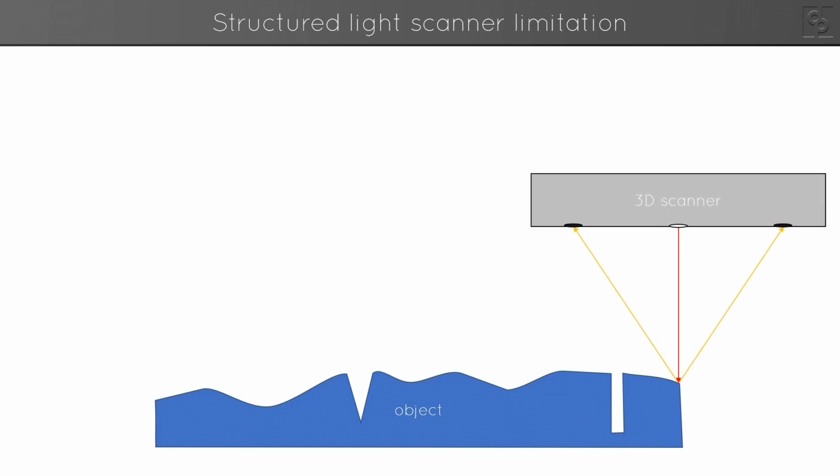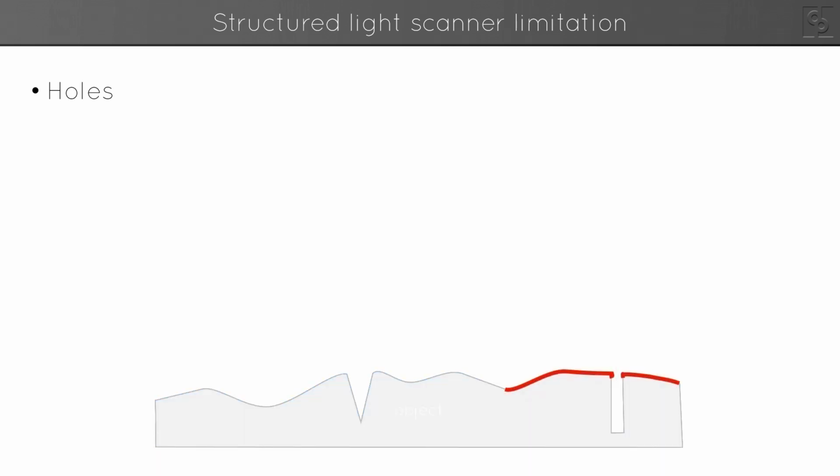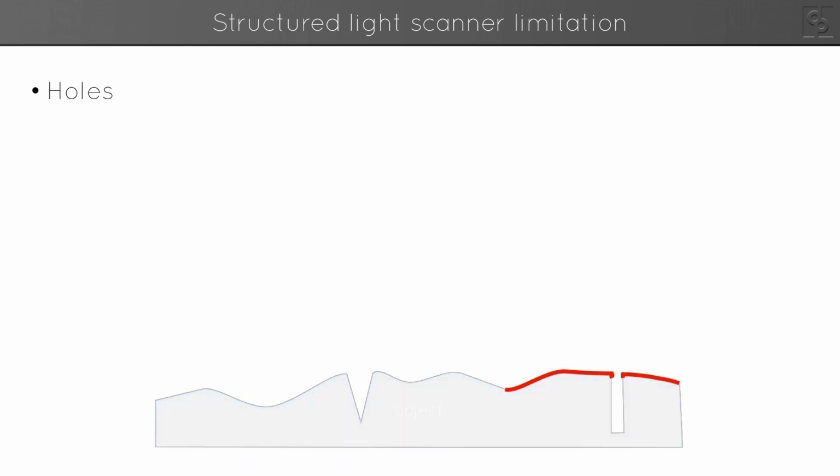When you're scanning a small hole, the only part of the inner wall that will get scanned is just around the top. There's no way that all 3 elements can detect the surfaces further down. You can tilt the scanner in different directions, but you'll still only capture the top edge, and this can be a problem if you need to model these holes in CAD. If the scanner doesn't detect the center position or the depth, what can you do? For the depth, you need to resort to a traditional depth gauge, which you can also use to double check the internal diameter.